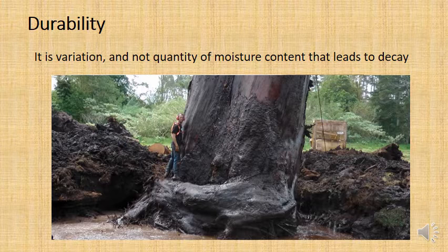They were completely wet. You can see that there. The moisture content was around 300% at the time. And we had to dry them out in a drying shed, as I said last lecture, for 2.5 years to get the wood to a good strength.